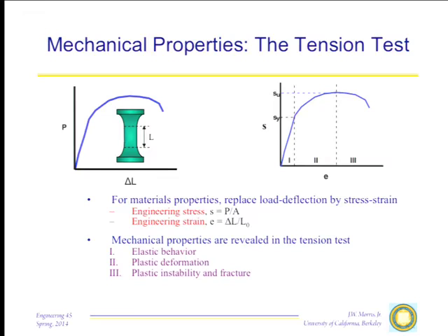You'll see that, I don't think you have yet, but you'll see it in the laboratory. We'll put in a sample, we'll pull on it. As the load increases, the sample stretches out. And the typical curve on that will look something like shown at left here, where you have a linear region that starts off. This is for a typical ductile metal. It then loses its linearity, peaks out, drops off, and finally fractures out here at the far end.